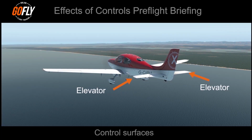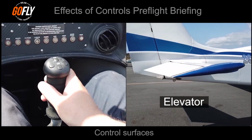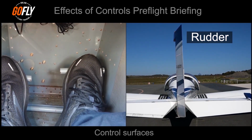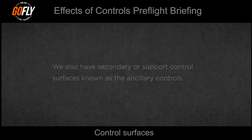The main control surfaces are the elevator, the ailerons, and the rudder. The elevator and ailerons are controlled with our control column or control stick, and the rudder is controlled by our rudder pedals. We also have secondary or support control surfaces known as the ancillary controls.